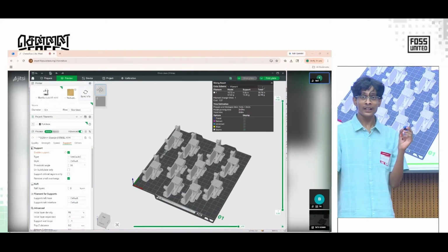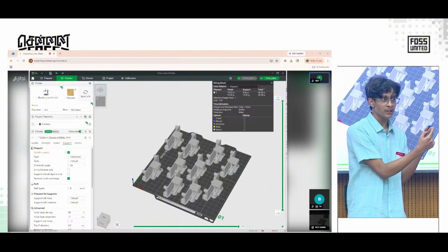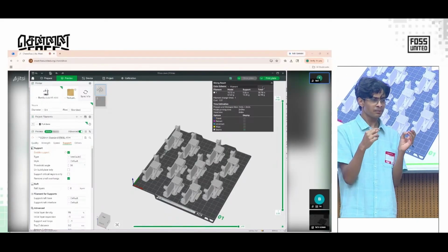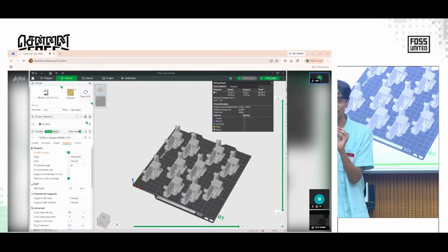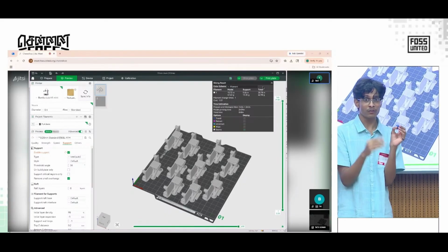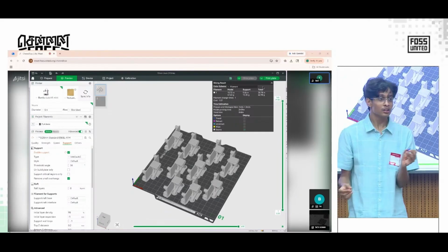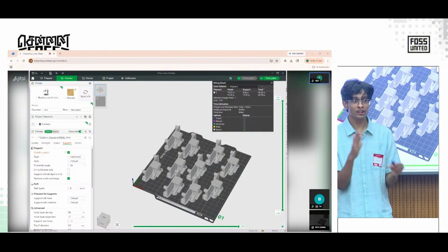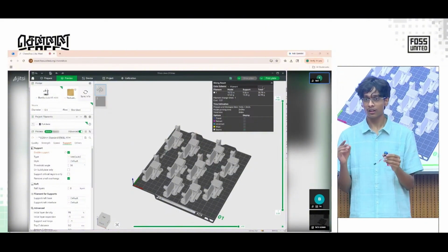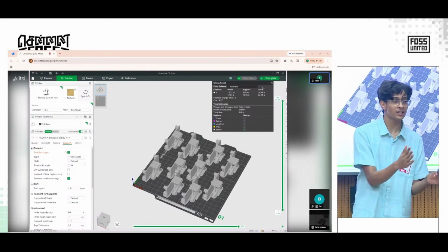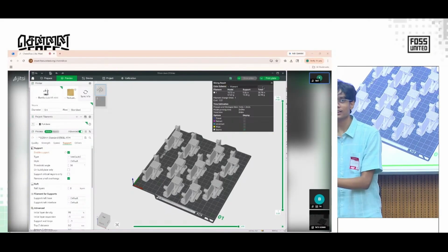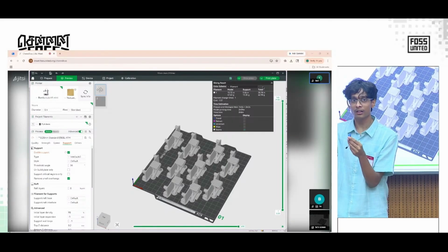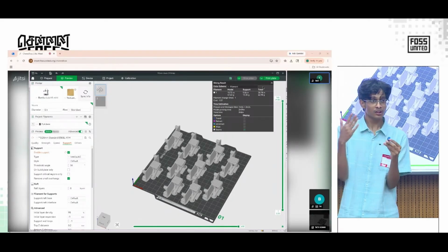Now, if we completely block off the links to this potentiometer, there is a plastic piece which screws into the potentiometer. That's how it knows which angle it is positioned at. So we cut that off, and now it is a 360 degree servo motor, so you can control the speed. Normally, if you program the servo to move to 20 degrees, it moves to a 20 degree angle. If you want minus 70 degrees, it moves to 70 degrees the other way. That's how it works.